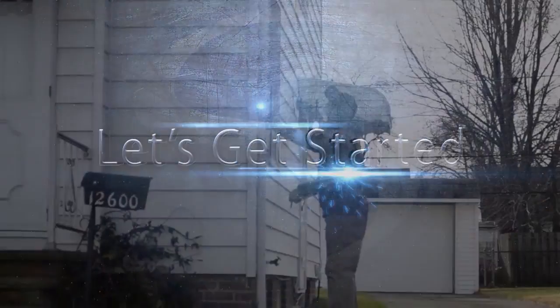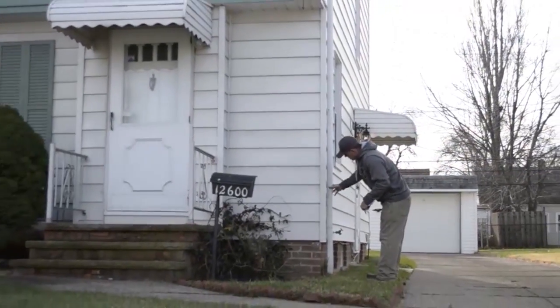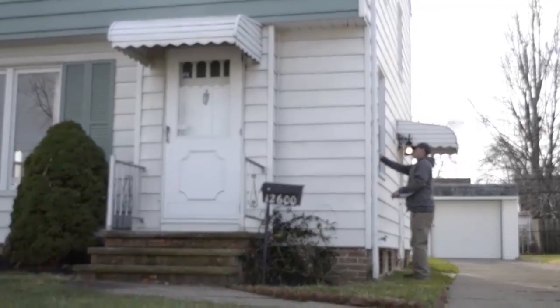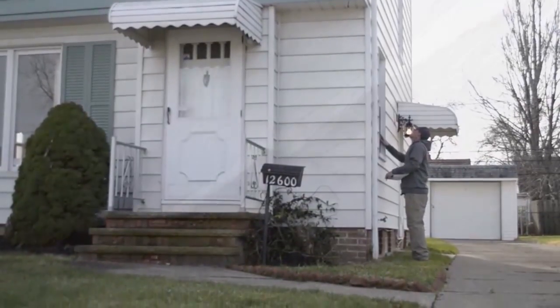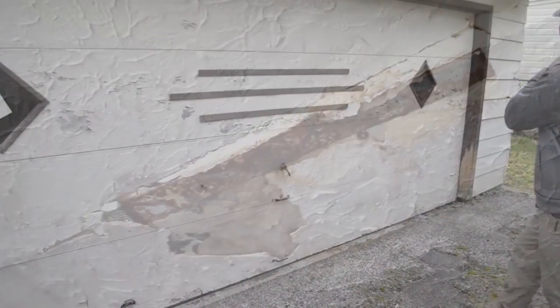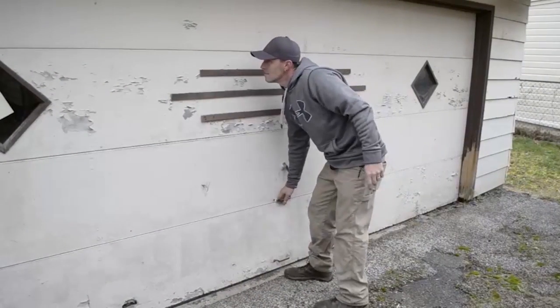Let's begin. When water stains and/or mold are found at a property, the first step is to identify the source of the water stain and the mold, which will always be some sort of water intrusion. The source can be a variety of things. Let's take a look at each source possibility.